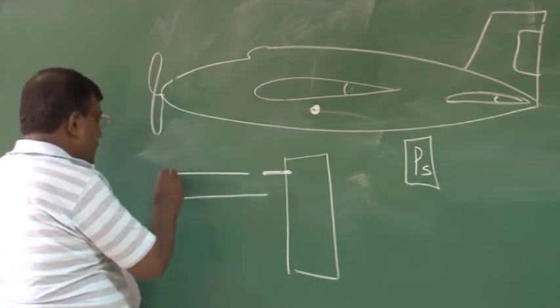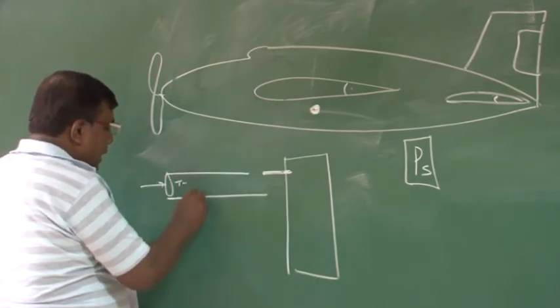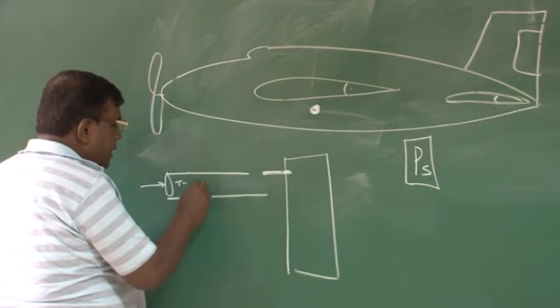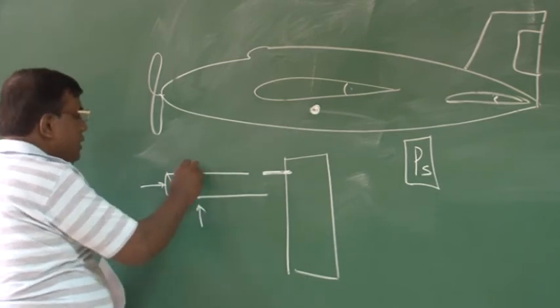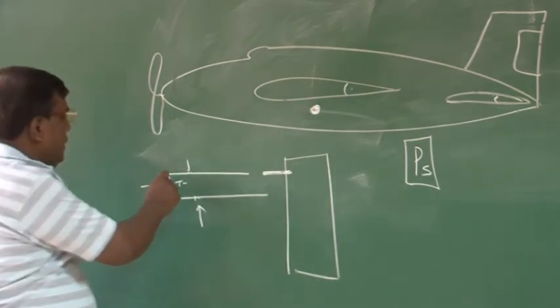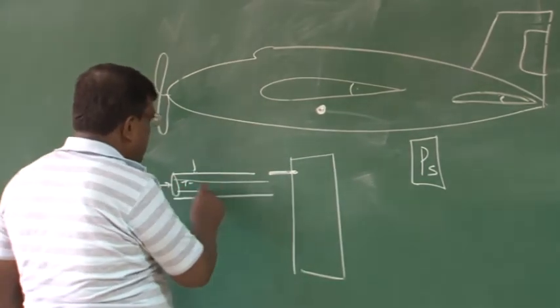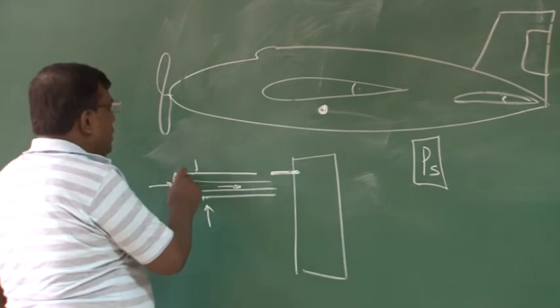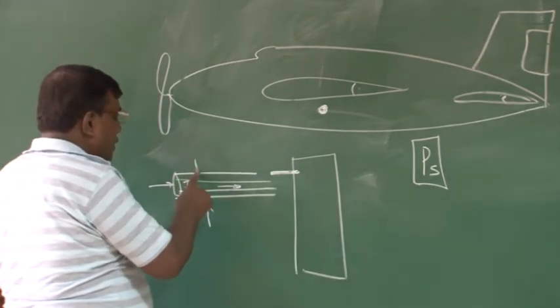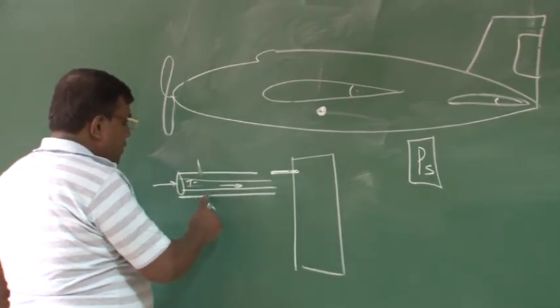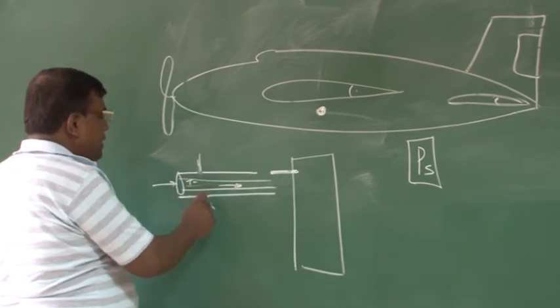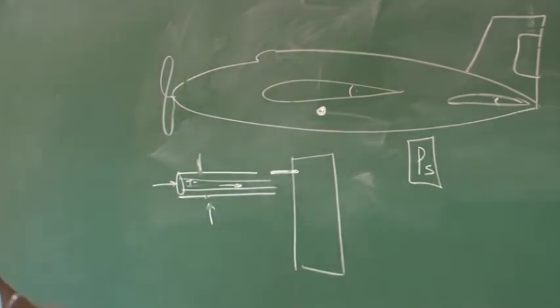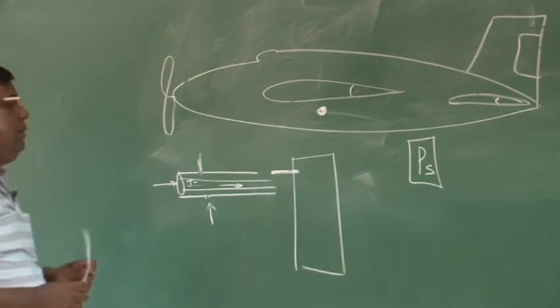So this is the inlet for total, and there will be some gap here from where the static input will go. Okay. So basically there should be two tubes like this. From here, whatever is going inside is total, and from here, if I keep a slight opening here, this static pressure would be measured. There are many variants, but what is important?